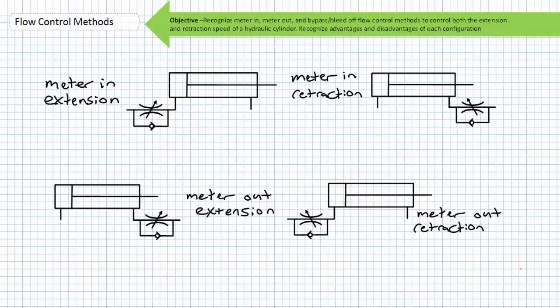This is to suggest that restriction-style flow control valves and direct restriction flow control methods work in combination with the pressure relief valve. Flow in always equals flow out. This is kind of like the Kirchhoff's current law of hydraulics. Incoming flow has to go somewhere. That flow not admitted through the flow control valve is relieved at the pressure of the pressure relief valve. When pressure drops without having accomplished work, there's a rise in temperature, a form of inefficiency.